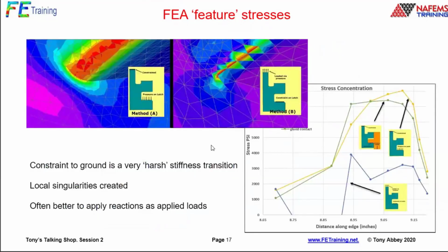This again is another example of high stresses. What I've done in here, this is basically a loaded latch or rim. I'm pulling down on this flange, I should say. Here's an even pressure distribution. That's the stress distribution coming up. The actual run out of the loading is just somewhere about here. This is actually constraining to ground. So this is glued to ground, infinitely stiff, and that's actually a stress singularity running through there. There's a different scaling value. This is off to infinity.